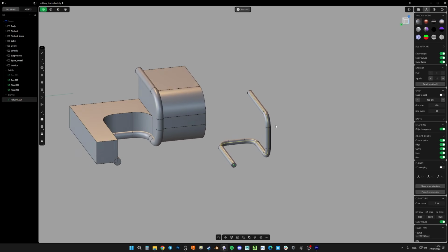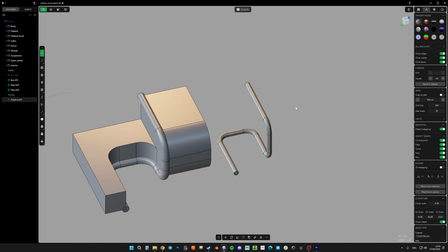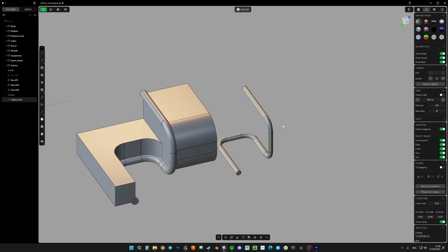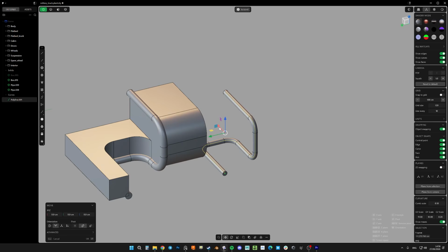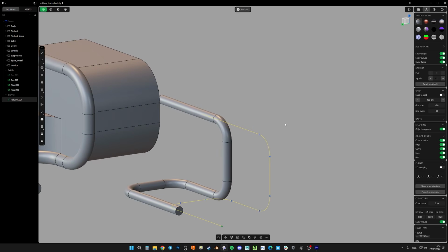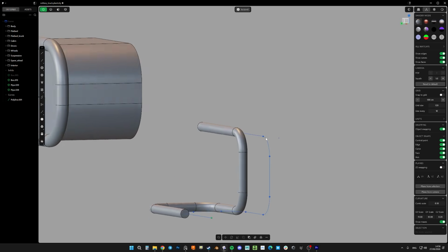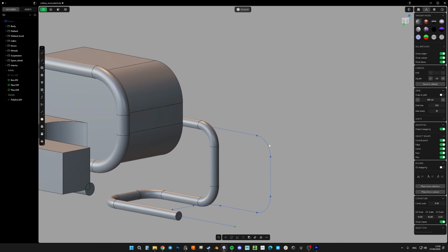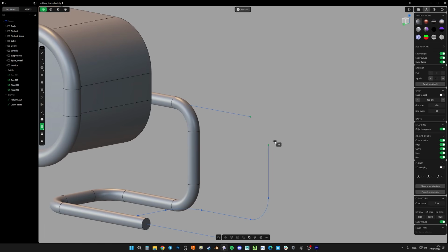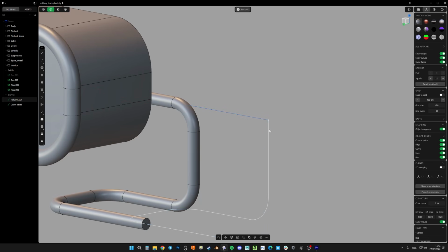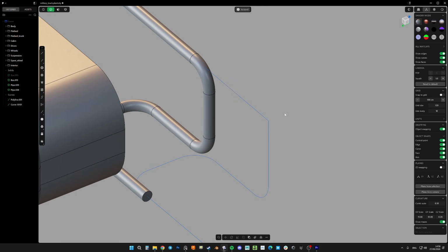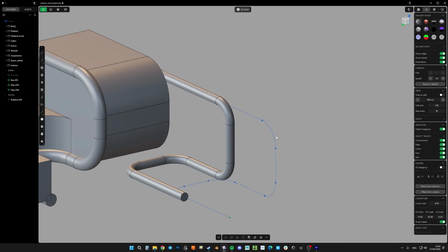In case of the second method, the advantage is when we build something, it's easier to visualize the final result and make adjustments along the way, but it's harder to, for example, adjust the fillet radius, because in Plasticity, as for now, it's fixed, and all you can do is, I don't know, manually delete it, rebuild, rejoin, and then make it from scratch. Which is very time consuming.